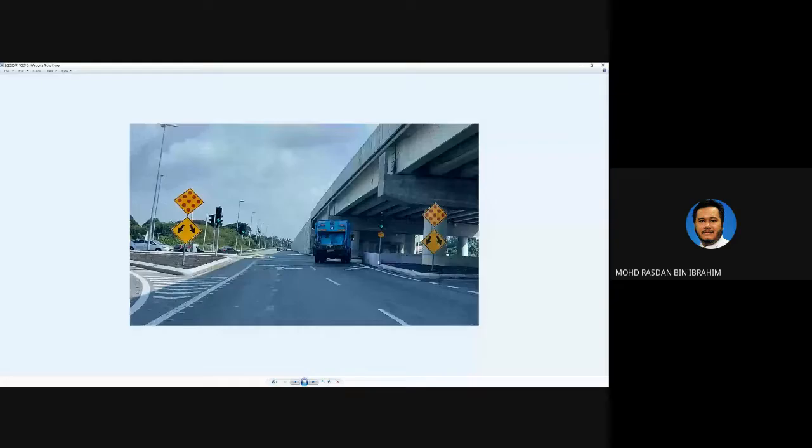Okay, for example, let's just imagine that this is a pier. So this road is very close. In this case, we do not need the guardrail barriers because it is at the stop sign, and this is quite far. But if this pier is very close to the roadway, for example, you need to have guardrails over here. Of course, this is a large pier. It does not mean much if it is hit, but we still need to protect it.